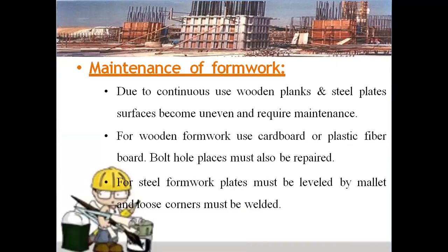Maintenance of formwork. Due to continuous use of wooden planks and steel plates, surfaces become uneven and require maintenance. For wooden formwork, use cardboard or plastic fiber board. Bolt hole places must also be repaired.